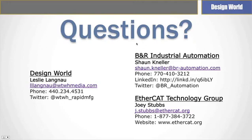But with Ethercat, because it's full duplex, you don't have to wait for a frame to return before you send another frame, so you can actually pipeline multiple frames over the wire without waiting for the return frame. So you can actually get a higher scan rate than just traditional polling.